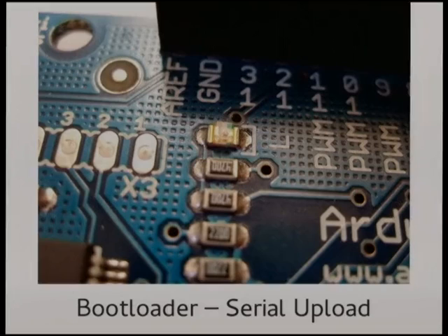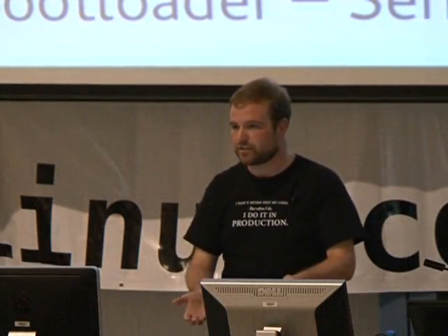That's because the way that the USB gets configured on the boards is such that it does the reset to run the bootloader, so you can then upload your program if you happen to be running the IDE there and trying to do an upload at the time. Because the IDE will open up the serial connection, and that triggers the reset, which runs the bootloader, so the IDE can talk to it. I hope that just made sense.